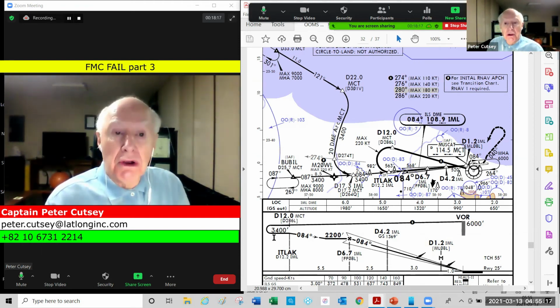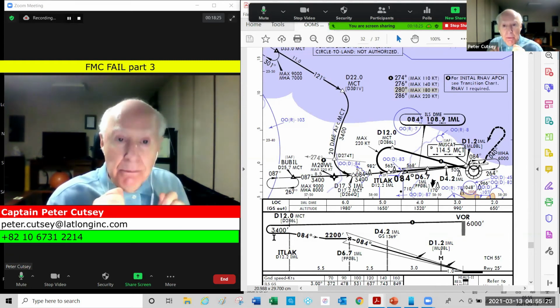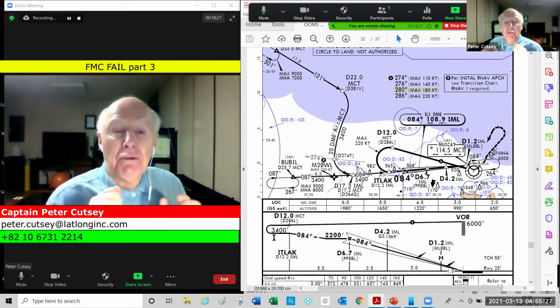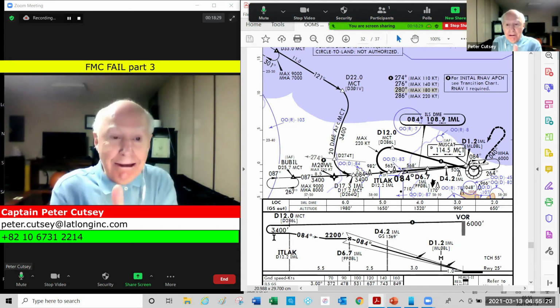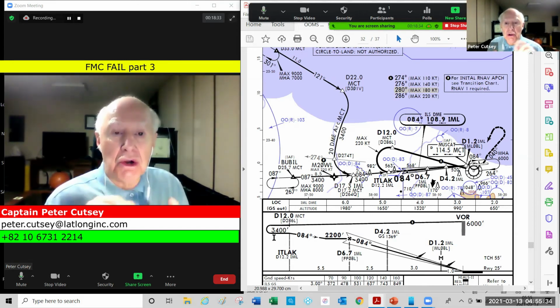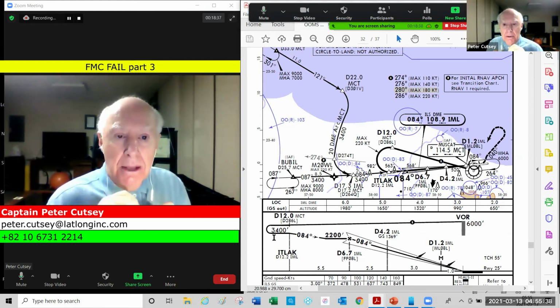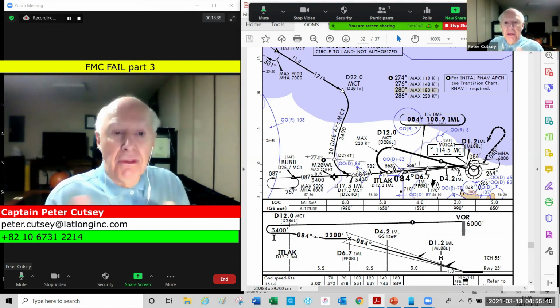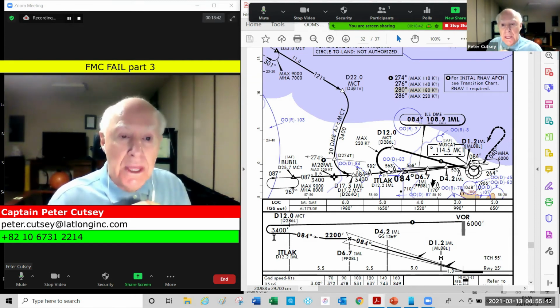You've got the autothrottles engaged. You've got the autopilot engaged. You're in VOR lock. So when you went by the MCT VOR on the heading mode, and give the radio a chance to align itself, then select VOR lock. Make sure you have a capture on your nav display and allow the autopilot to track the radio.